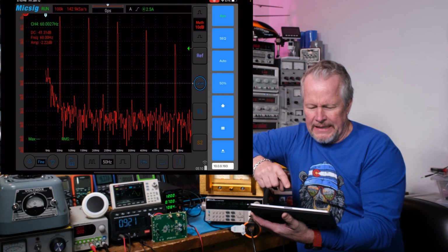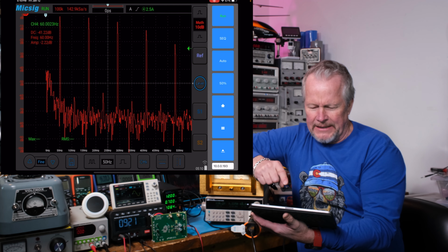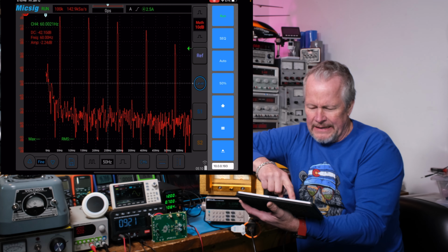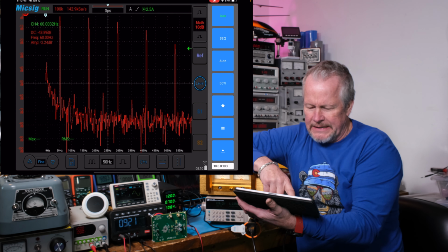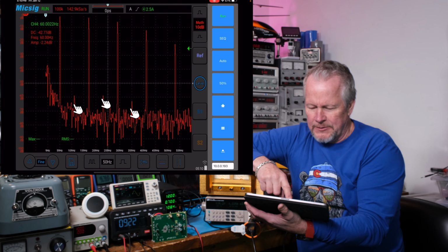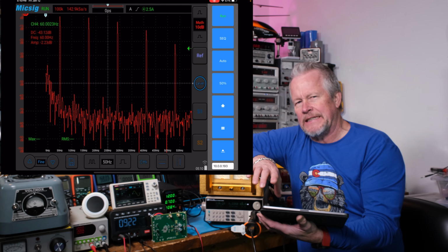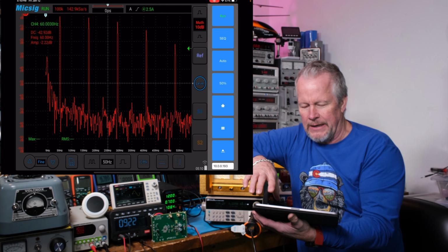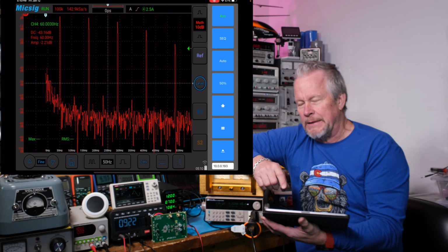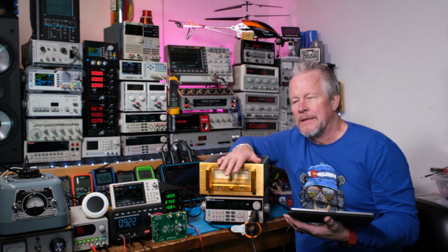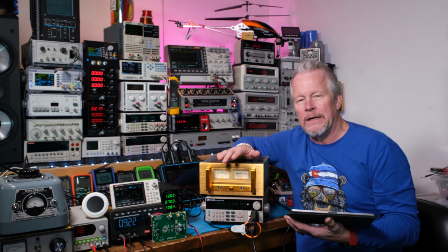So you see the first waveform, that's 60 hertz. Then the next one over, if you look down in the noise floor, you see those little spikes. You see little spikes in between the big tall ones. Those are every 60 hertz. So that's the 60 hertz harmonics, okay? But the big ones, because of the bridge rectifier in the Class A amplifier, and pretty much I would say most low frequency switching power supplies use a bridge.